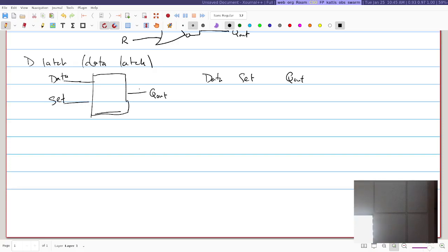Because otherwise, you would be reduced to trying to make every single pathway through the circuit exactly the same length, so that everything takes exactly the same amount of time to get there. That's, A, extremely tedious, and B, probably not even possible, because physically you just can't do that. So we need some way to say, okay, this signal came really fast, we're still waiting for this signal, but we know that everything is going to take at most this amount of time. This is what a clock is for.